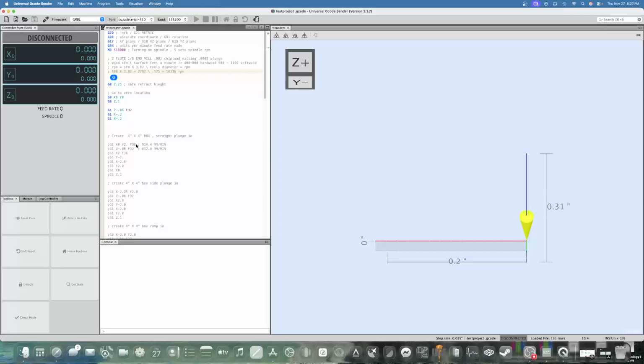If your wood's really hard, you notice a lot of heat, you can smell the wood getting hot, slow that RPM down. If you're getting, I guess you call it fuzzies on the softer wood, and it's cutting fine, speed that RPM up. You get a better surface finish. You just got to play with it a little bit. It's always a vast range.